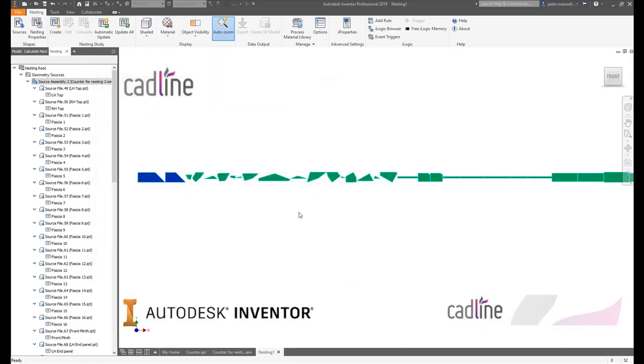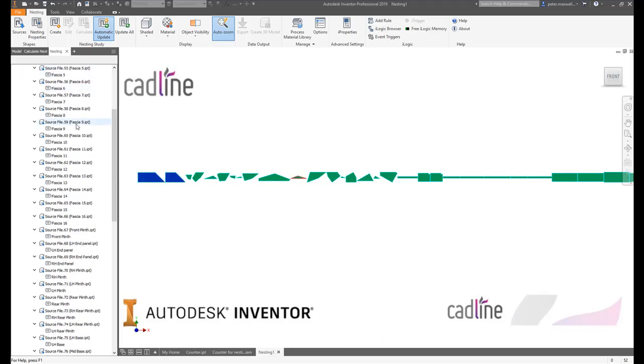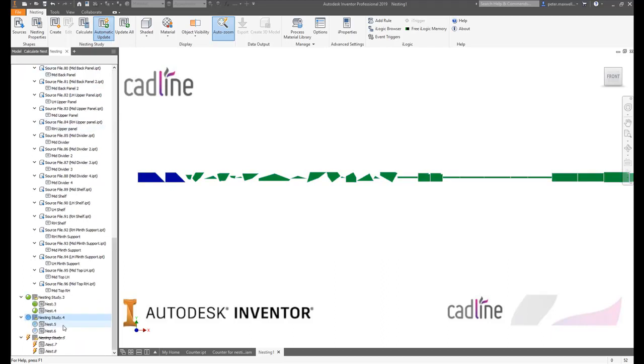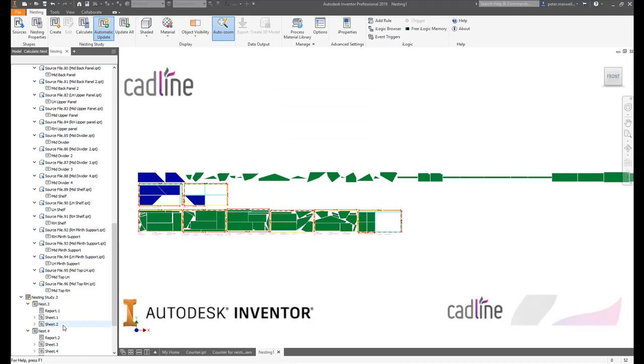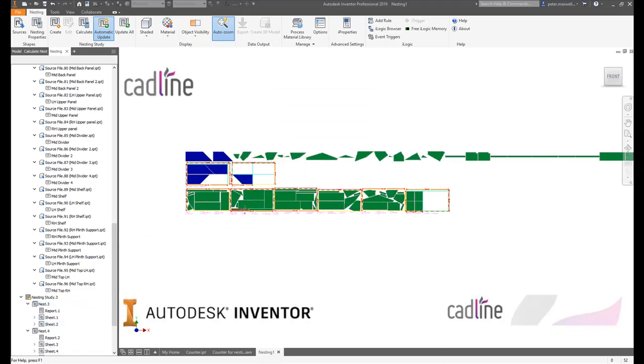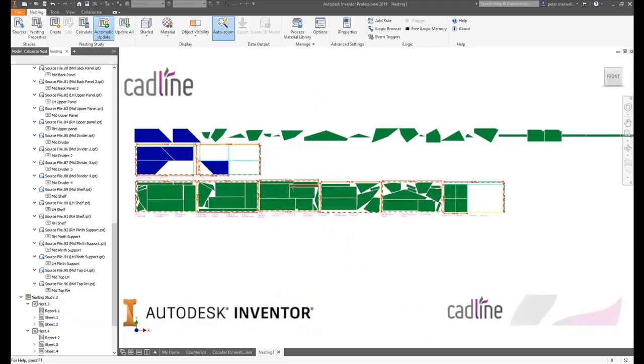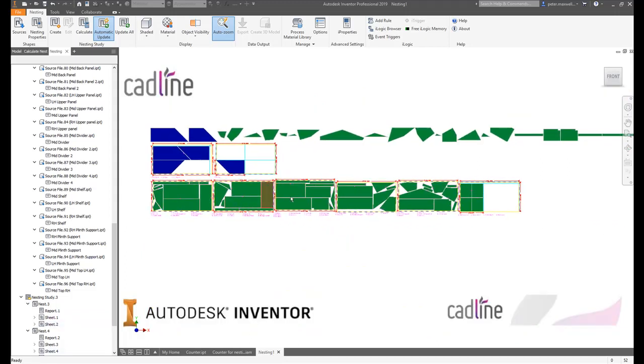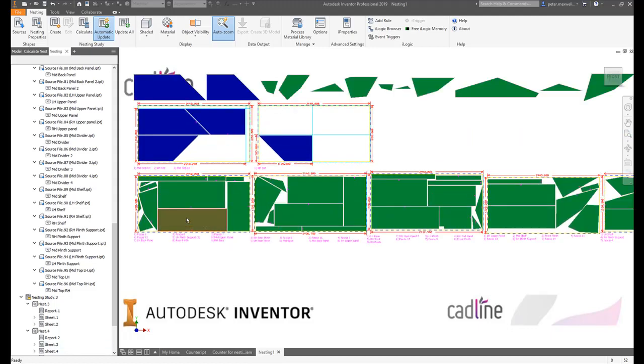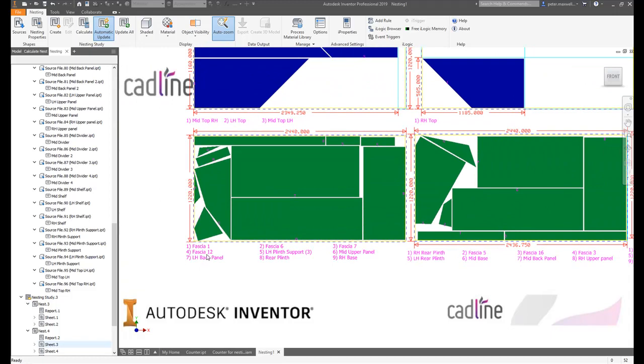And then this time, there we go, brilliant. So you can see here that it's split up our countertops, and we're going to need 2 sheets of ply to do that, and for this one we're going to need 1, 2, 3, 4, 5, 6 sheets of 80mm MDF to fit all these pieces on, and it lists the parts that are on each of those sheets.